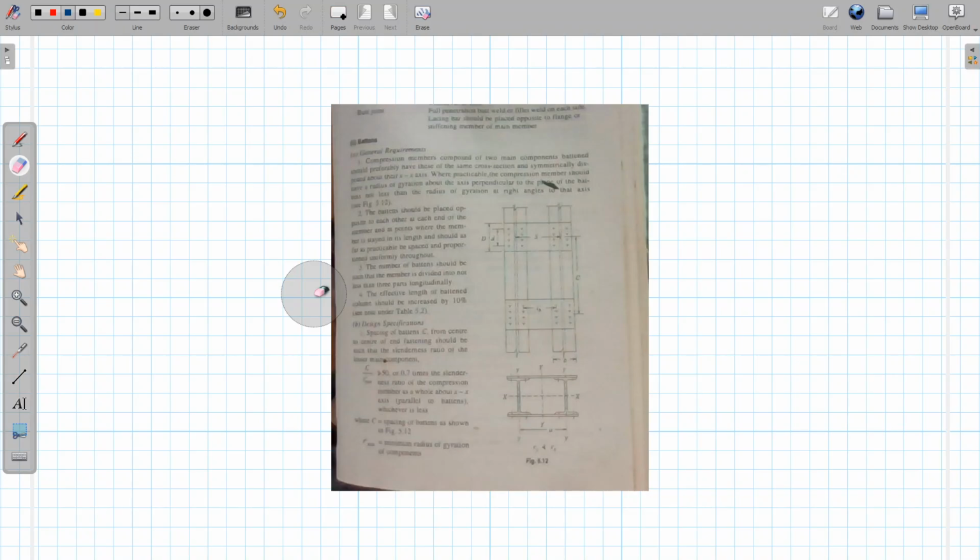Okay. Now see, in this case we are getting two pieces of information. One is the longitudinal shear and another is the moment. That means if you go for an eccentric connection, suppose you are doing a riveted connection, then you consider it as an eccentric connection with direct force V1 and moment M. So for that case, you assume some rivets with some diameters and find out the rivet value.